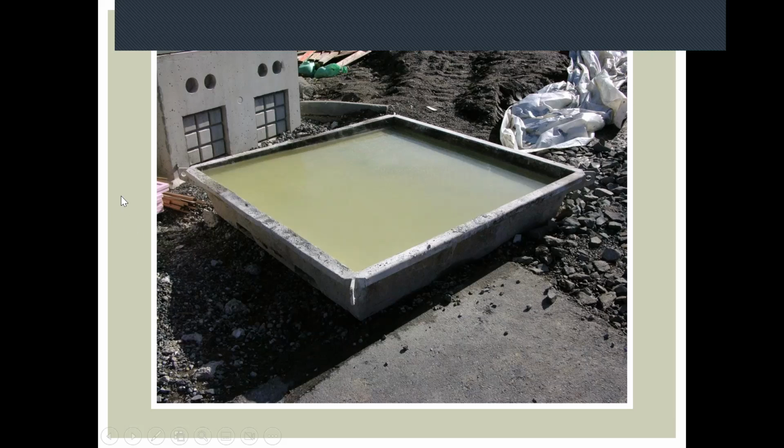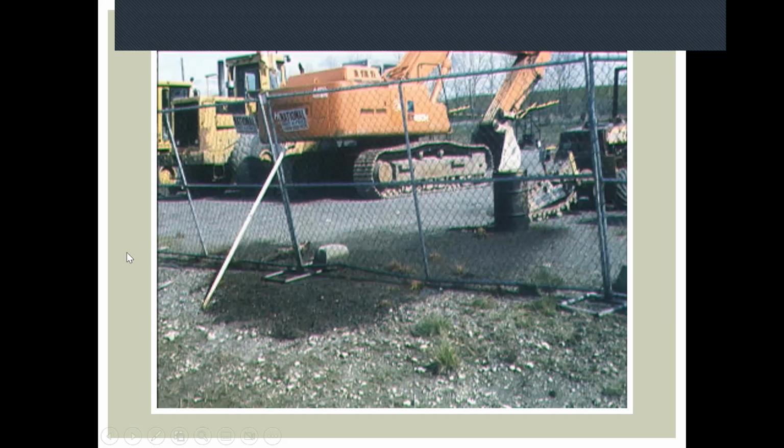So here's the standard practice for washing out concrete trucks or chutes, but be aware that they do fill up. You can pump the water and slurry back into a truck. I've seen this done, but don't let it get over full because the pH on this stuff is really high and will cause problems. So just make sure the contractor is staying on top of these sorts of things and getting them serviced before they get to this point. Look for things like this, staging area covered with crushed rock, and then here's this big dark area. What's going on?